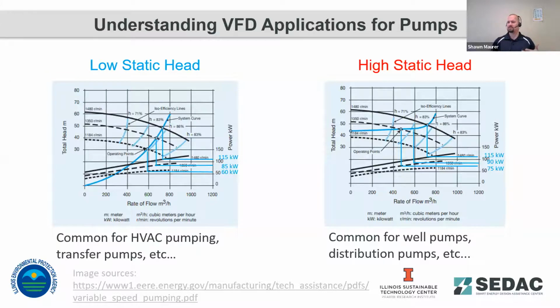So understanding what type of pumping system you've got before you start looking at a VFD application can help you determine upfront whether it's going to be beneficial for you or not. And what we tend to find is that for well pumps and surface water pumps drawing in, there's generally a good VFD application there.